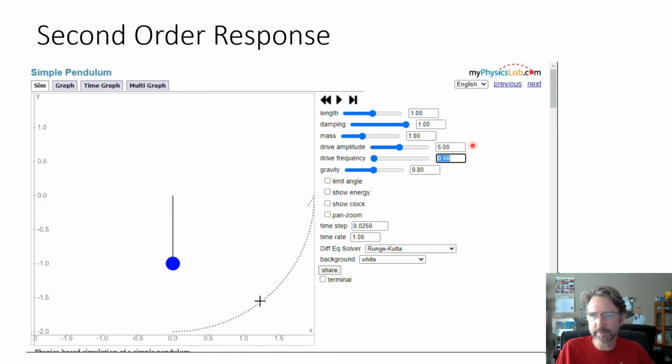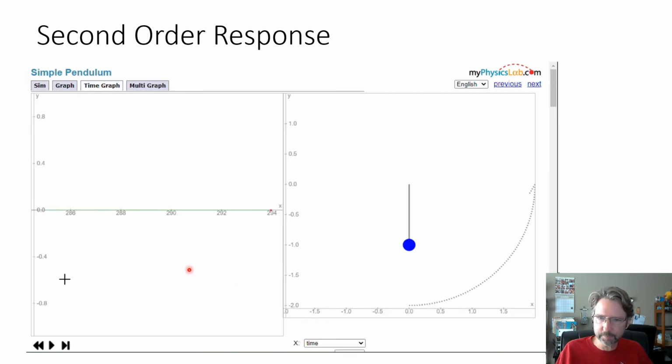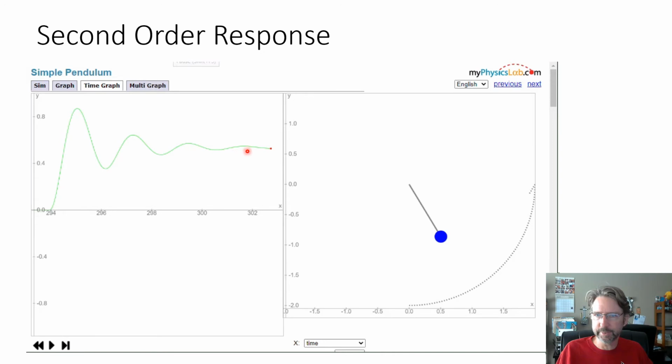It's a canned simulation, but you can see the gust is going to make it tilt this way. So here we're going to turn the gust on. You can watch the response. So this is swinging out to measure the wind. It's a sensor, and you can see the angle here. It has some overshoot, and then it decays down to this steady state value at the end.